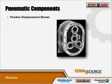So the positive displacement blower is going to deliver a constant volume of air. Inside that blower, you have impellers rotating at close clearances to the housing for maximum efficiency. There's the housing. Over time, those clearances are going to increase, which reduces the efficiency. You might have to rebuild the blower at some point.